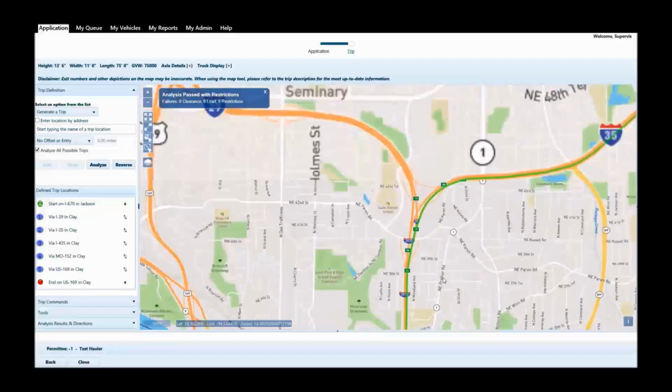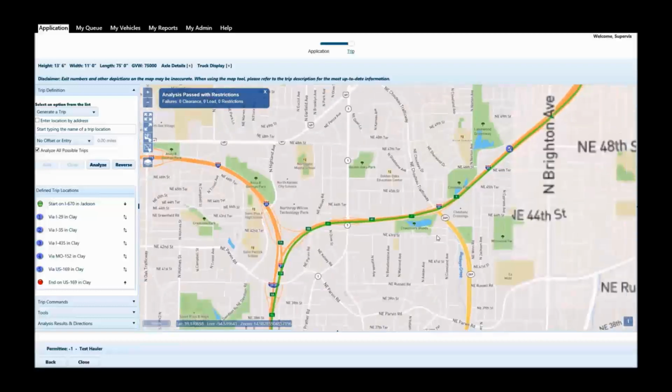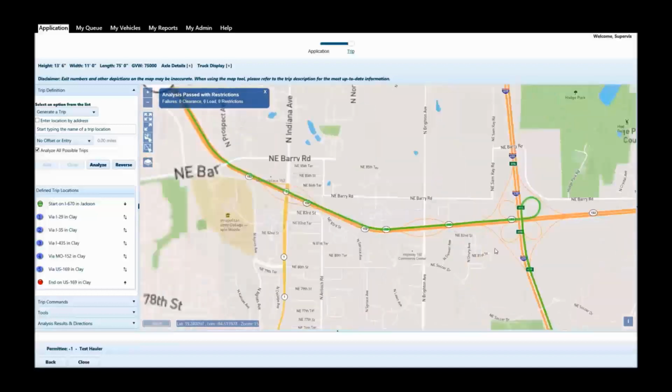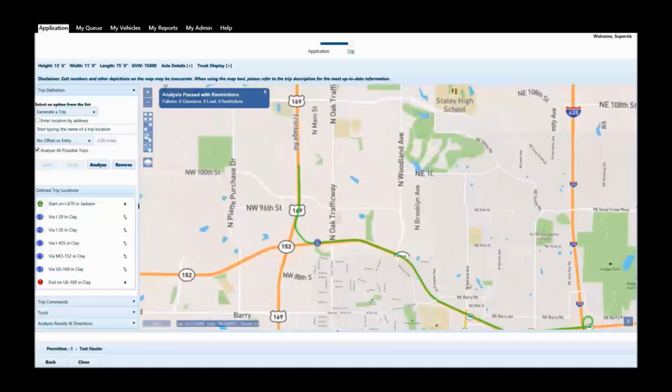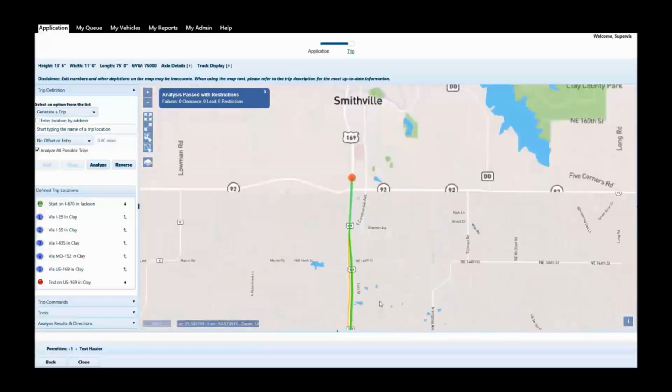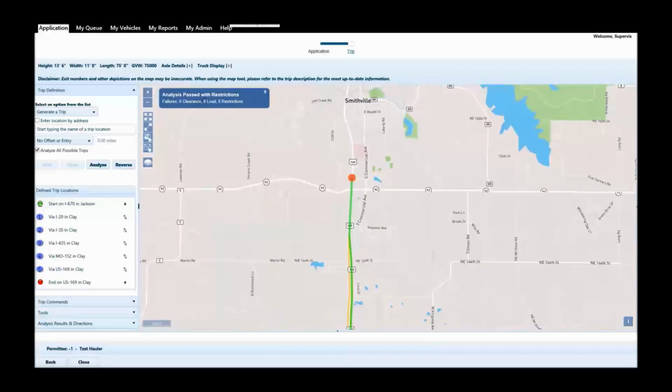We do a whole lot of pretty intelligent, multiple types of selection to best determine that direction of travel. Should you be coming in specifically from one road to another right at a crossing and need to say, I'm starting this going this direction, then you can use some of the entries and offsets in the panel in a command. But otherwise, if you're just saying, hey, I'm on State Route 1 and I'm coming in off of this driveway, you may be able to go left or right off that driveway, and we automatically try to figure out which way is optimal.